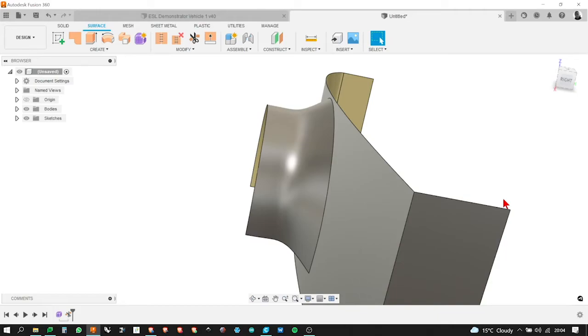What about a pinch job, where you overlap, you've got an error, and you use the same technique to cut away the bits you don't want? No, because it won't come out of the sculpting or the form environment. It will say there's an error and it won't turn it into a surface. Otherwise, you should be able to, but because it's a self-intersecting surface, the maths engine obviously can't cope with that. So, yeah, but if it could, then you could.